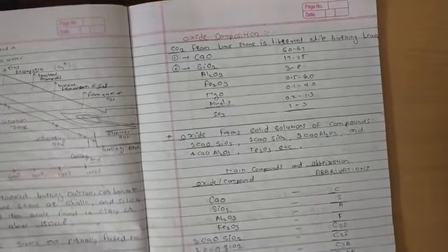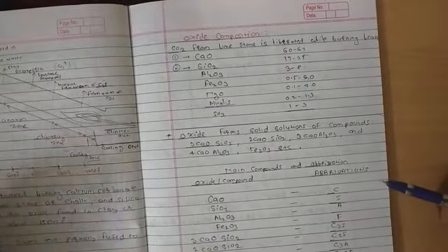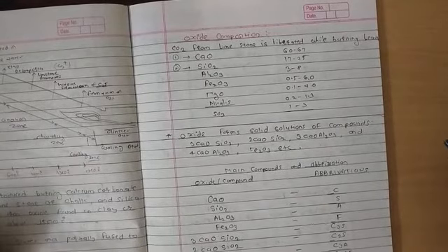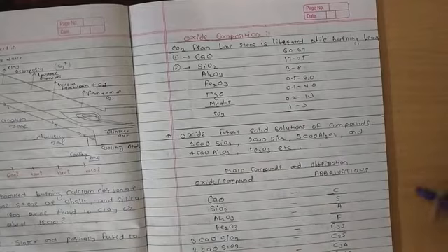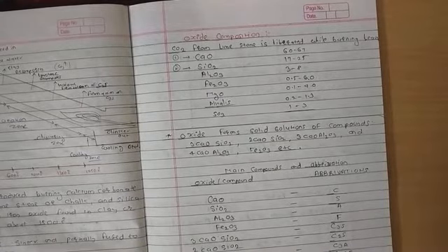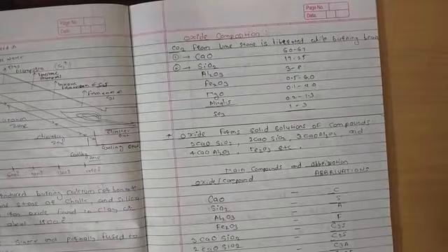We have to use these compounds many times, so it is not possible to always go through the chemical formula. So we use abbreviations, for the sake of easiness. It is very difficult to always say SiO2 of 17 to 25%. So for ease, we say silica as S. These are the abbreviations: calcium oxide as C, SiO2 as S, Al2O3 as A, Fe2O3 as only F.